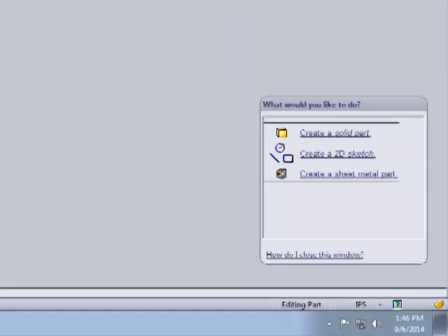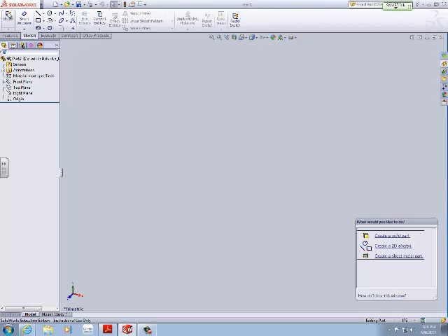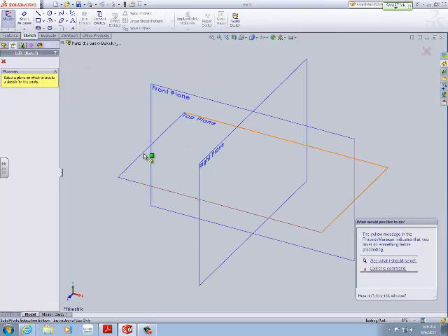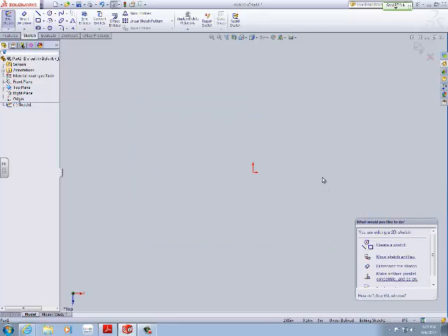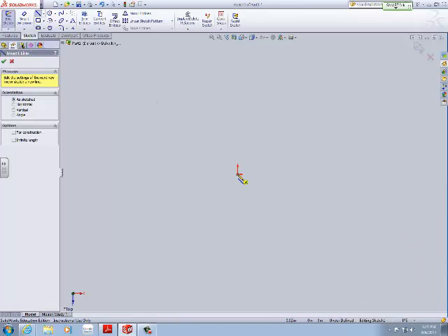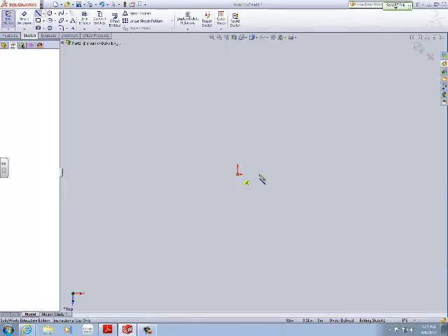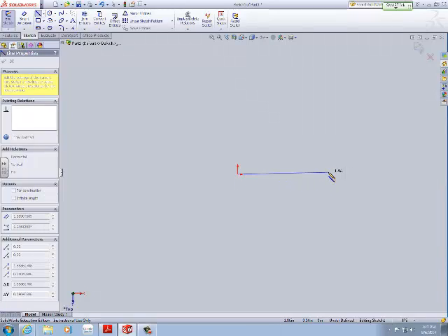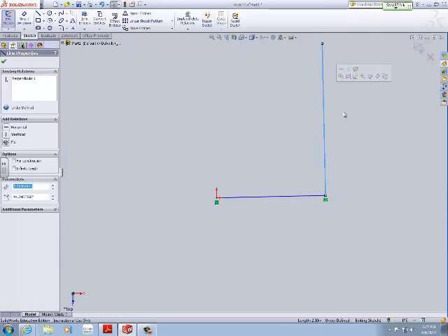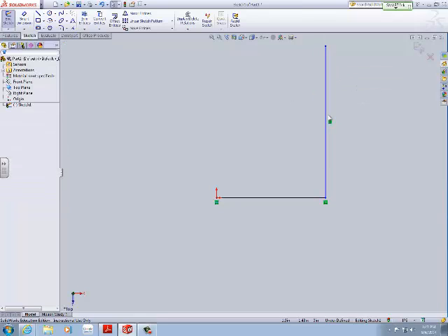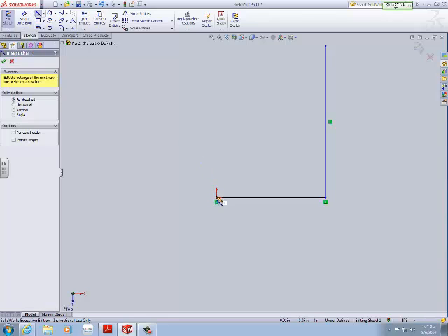So basically what we want to do is go to Sketch. We select Sketch, we select the top plane. From there, we're going to draw, actually just use lines this time. Lines from origin, so make sure that highlights. We're going to go horizontally, vertically. Oops, is that vertical? If it's not vertical, you can see it's kind of angled. You can select it and make it vertical, so that has an attribute. Do the same thing on the other side.